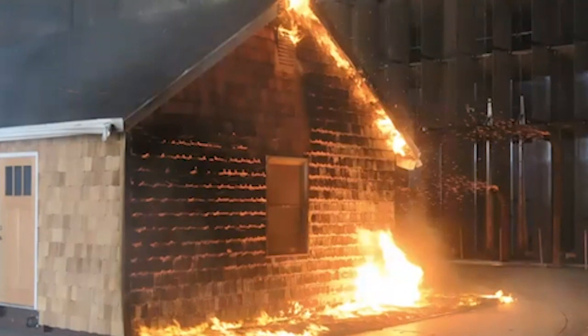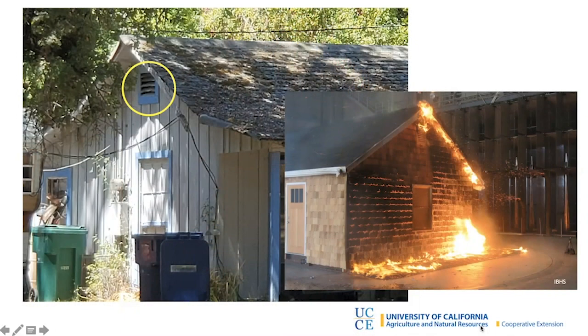So in the picture that has the gable end vent, clearly we don't have a non-combustible zone near the home, and we have some plastic containers. These can also ignite, and all of these things can provide a flaming source that can be pretty large to the side of the house. So scenarios where the flames can reach this particular vent are a number of them in this particular scenario.